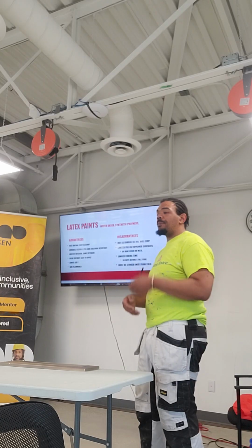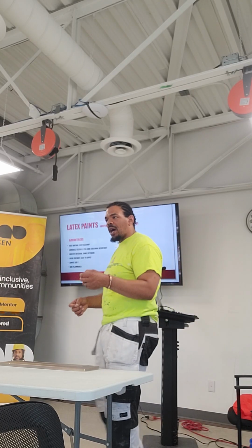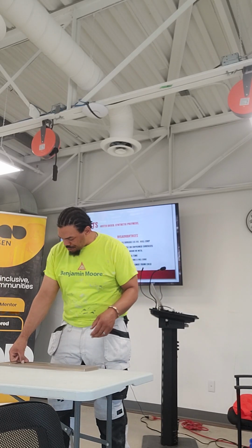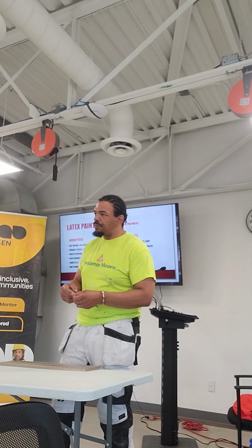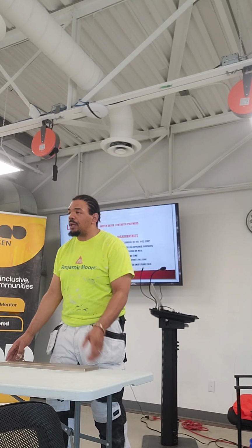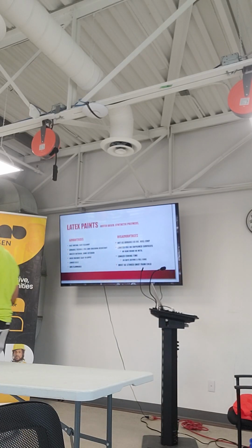Most people assume that the paint is dry, oh, I can just do whatever. But if you ever walk up to a paint that's been dry for a day and you try to put your fingernail through it, you can put your fingernail through the film because it's not cured. It might be dry to the touch, but there's something called a curing process.